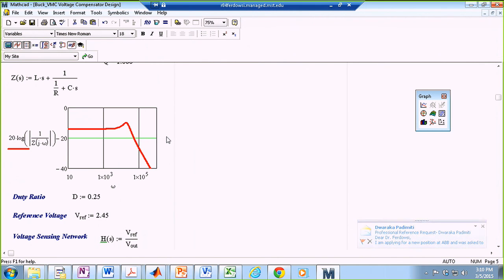So I'm running, for instance, the system at 75 kilohertz, then 75 multiplied by 2 multiplied by pi. We are looking at about 1,000,000 radians per second. So it's somewhere around here. And you can see at this particular, if I continue this to hit my switching frequency, you're getting a lot of attenuation. And that's good. That's why you were doing this.